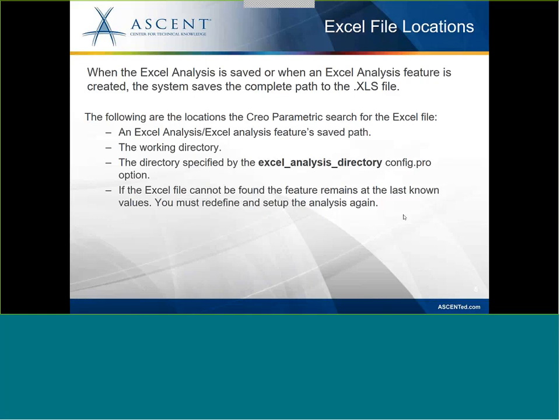If something happens and that Excel file is missing and Creo can't find it, your model won't fail, but it will simply regenerate with its last known values. If you then find that Excel file or create a new Excel file, you have to set up your analysis again.